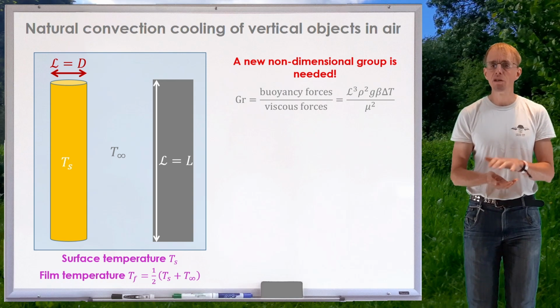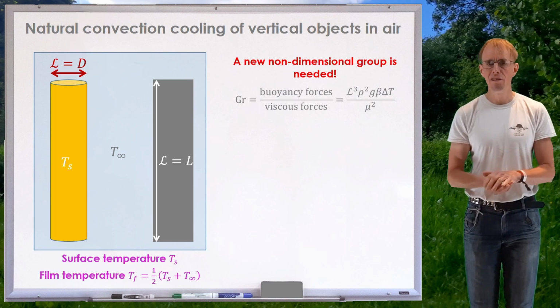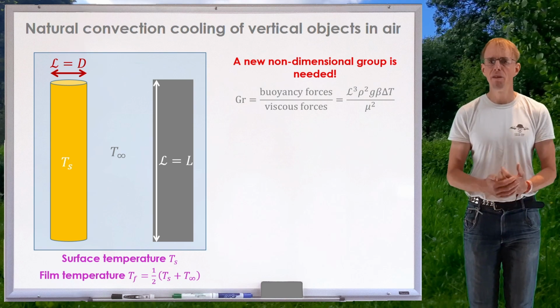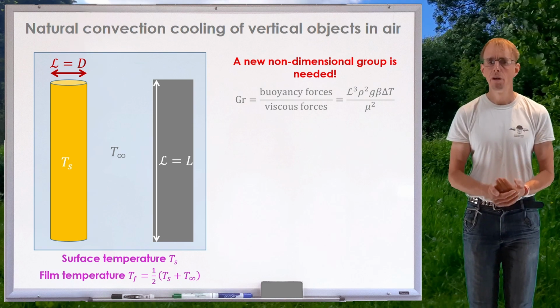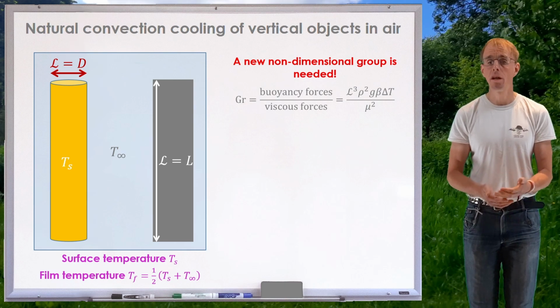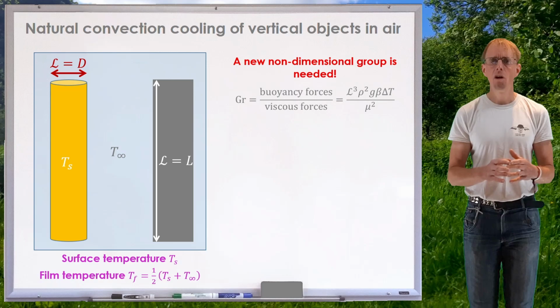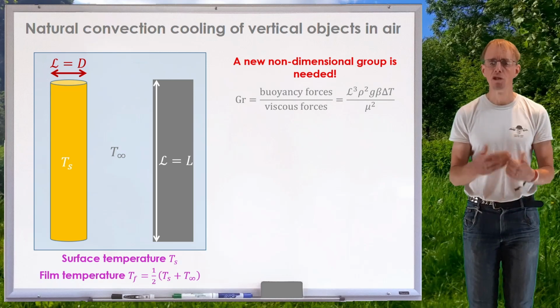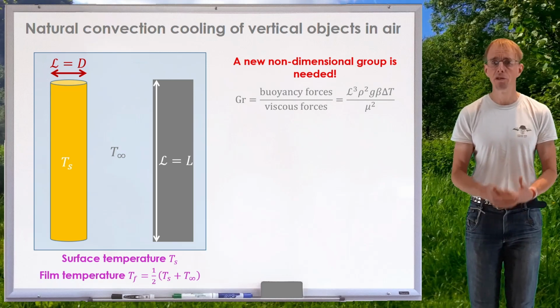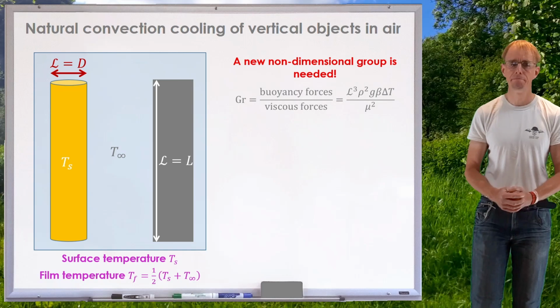If we imagine we've got a similar change in density due to temperature difference, but a very viscous fluid, we can imagine that the Grashof number is going to be quite low. And so again, we can get a mental model as to the extent of that natural convection circulation based on the physical properties of the system.